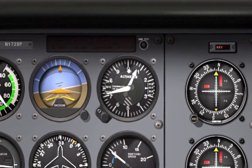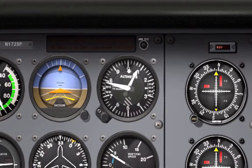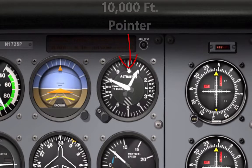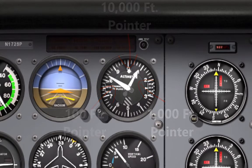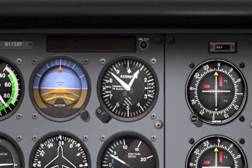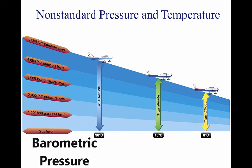The dial of a typical altimeter is graduated with numbers arranged clockwise from 0 to 9. Movement of the aneroid element is transmitted through gears to the three hands that indicate altitude. The shortest hand indicates altitude in tens of thousands of feet, the intermediate hand in thousands of feet, and the longest hand in hundreds of feet. Adjustments for non-standard pressures are accomplished by setting the corrected pressure into a barometric scale located on the face of the altimeter. It is easy to maintain a consistent height above ground if the barometric pressure and temperature remain constant, but this is rarely the case.